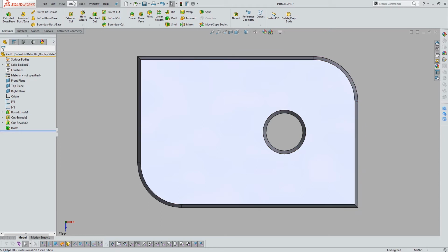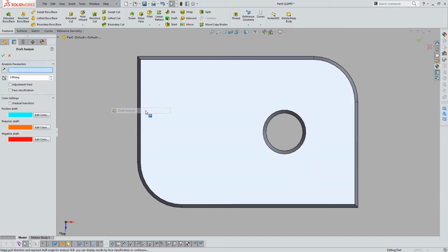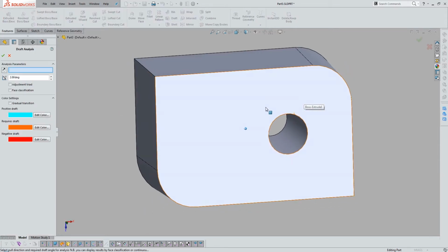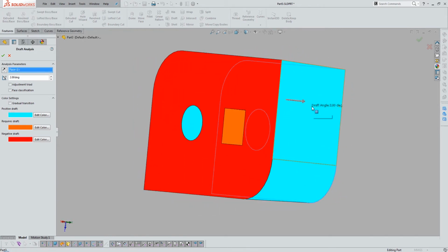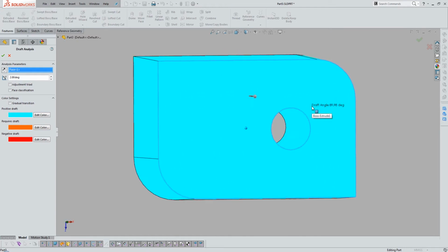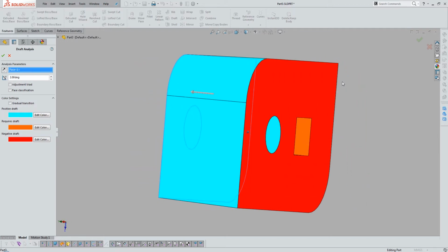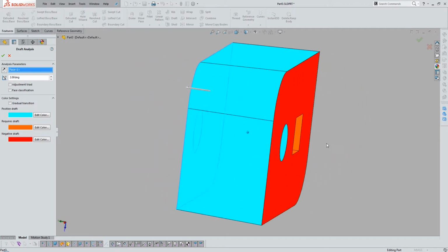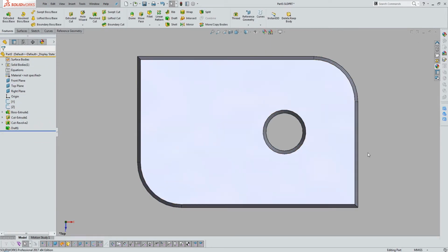see it. The SolidWorks draft analysis tool found in View, Display, Draft Analysis does exactly that same thing. Just basically looks and checks to see if it can see the face. Now, it works a little bit differently, and it will give you some potentially confusing results if you have more complicated geometry, but without using the draft analysis tool, the best way to do your draft analysis is just by using your eyes. So I'm going to flip this part over.